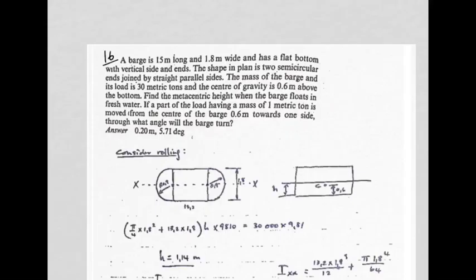So by seeing that this metacentric height is 4 meters and the other one is only 0.864, it would suggest the vessel is more stable in pitch than in roll, which would make sense for a vessel shaped like this.